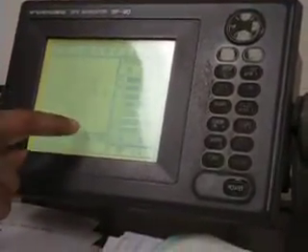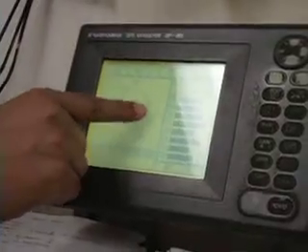in this page there is a picture coming. Can you see that one? Yes, sir. Okay, so 4, 17, 13, 23, 20, 32, 31, 01, these are circled. Means these numbered satellites are being tracked. My antenna is getting a signal from those satellites. The ones which are not encircled, like 12, 10, 11, the satellite is there, but the machine is not getting the signals. So from here we know which satellites at the moment: 1, 2, 3, 4, 5, 6, 7, 8. 8 satellites, which is very good. Minimum required 3.